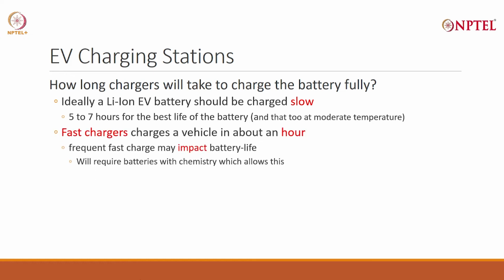You can do fast charging. For example, 1 hour charging is possible. But it will impact the life of the battery. And remember, battery is expensive. Any attempt to fast charge will hurt the battery. You have to take a call. Once in a while, therefore, you can do fast charge. If you want to do it regularly, you will get into problem.